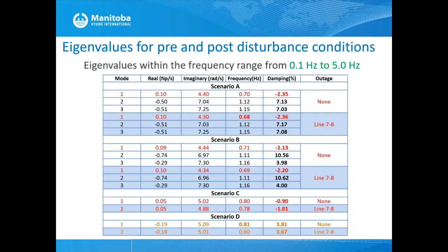The eigenvalue for the asymptotically damped mode, which is not oscillatory, has only a real number. For an oscillation, the real part of the eigenvalue is actually in Nepers per second. That indicates the amount of damping. There are 2 more questions.